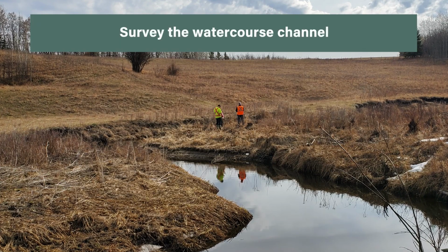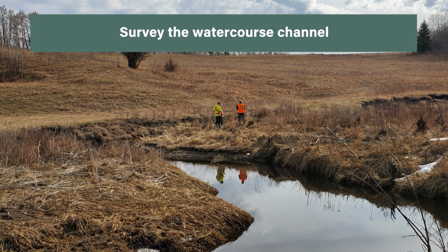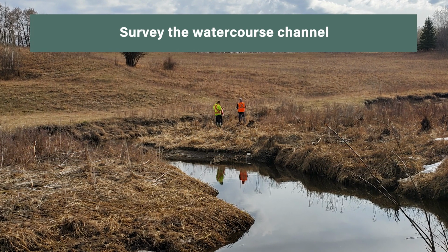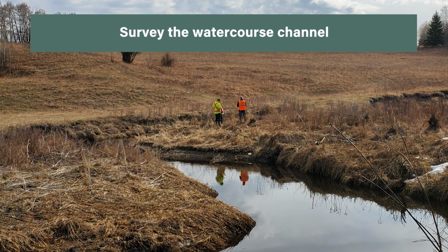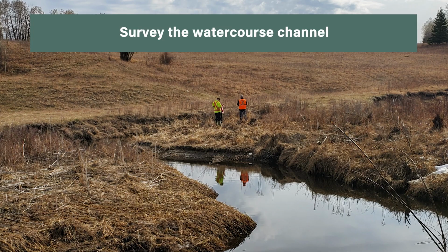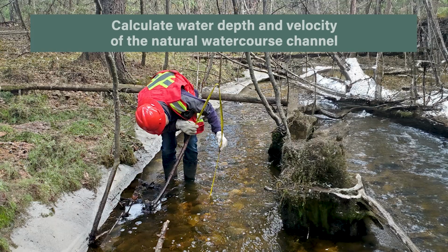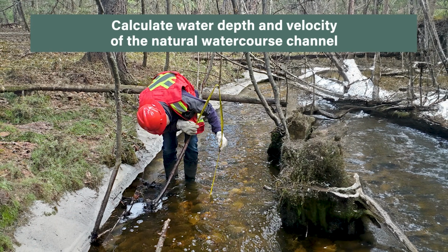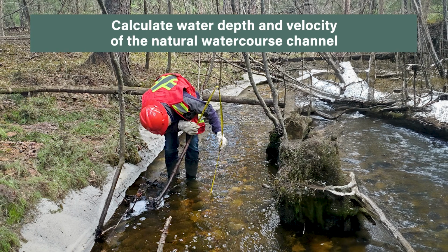Survey the watercourse channel at the watercourse crossing to determine the slope, width, substrate, and other features such as bedrock outcrop locations. Ensure that the width measurements include the bankful width and active floodplain. Select a crossing structure type, size, and configuration. Calculate the water depth and velocity of the natural watercourse channel, and for the selected structure style and size.